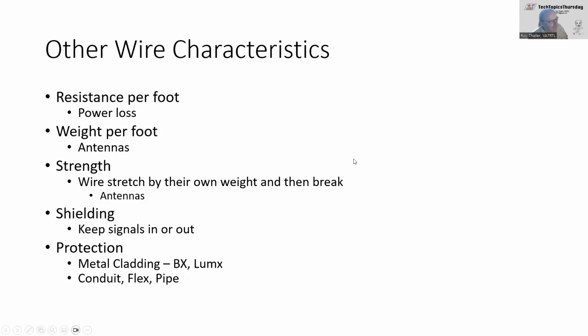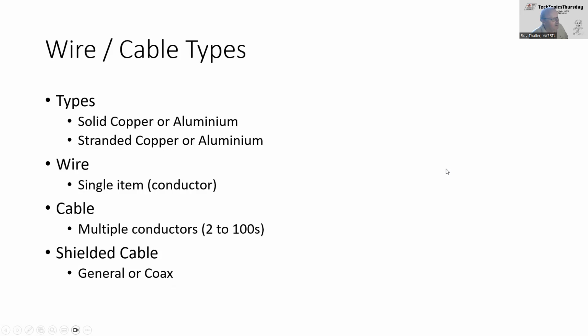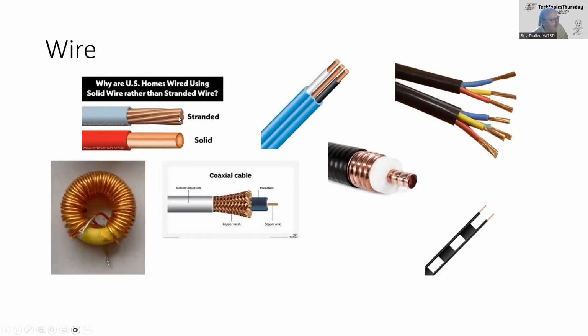The other thing is wherever you make a connection to the wire or connect it to something, if you strip away the insulation on the wire, like if you go back to the picture here, this is usually the part that is mechanically unstable, and this is where it tends to break.